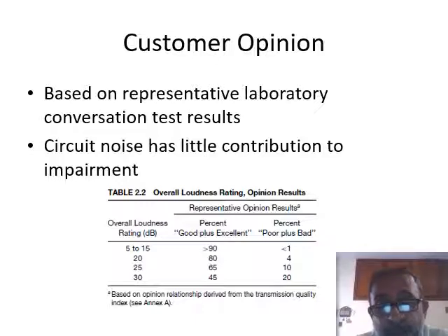But as the overall loudness rating increases, the people who like the service tend to decrease, and the people who hate the service tend to increase. So we should keep it to a minimum. Between 5 to 15 dBs is a good choice.